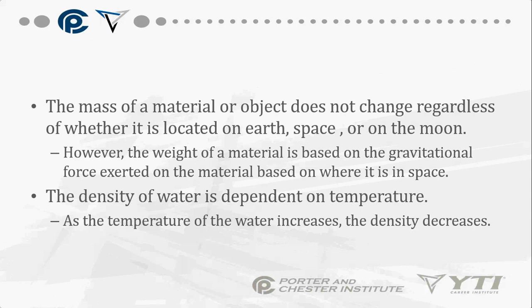Okay? Now boilers, they're going to be at a higher pressure. They're going to be somewhere around 10, maybe 15 pounds per square inch when they're actually up to temperature and running. So what does that do with your molecular motion and movement of the water?